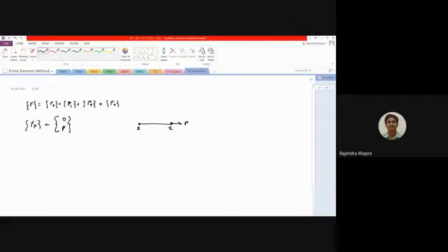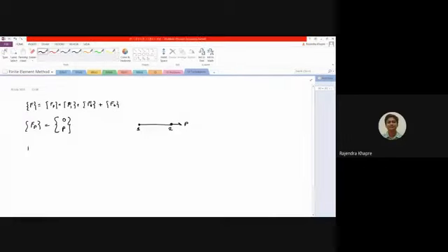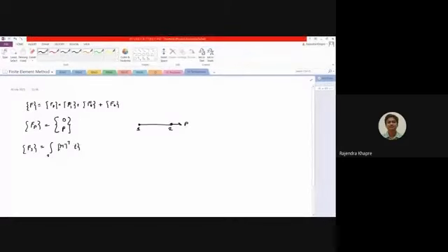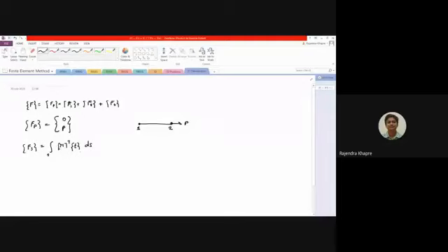But when it comes to the surface load, so this is your surface load. In that particular case, you have to go for some small integration, that is integration over the surface. We have this N transpose, where N is nothing but your shape function, multiplied by, let us say, I'm using a symbol T. T is nothing but your surface load, and this has to be integrated over the surface.